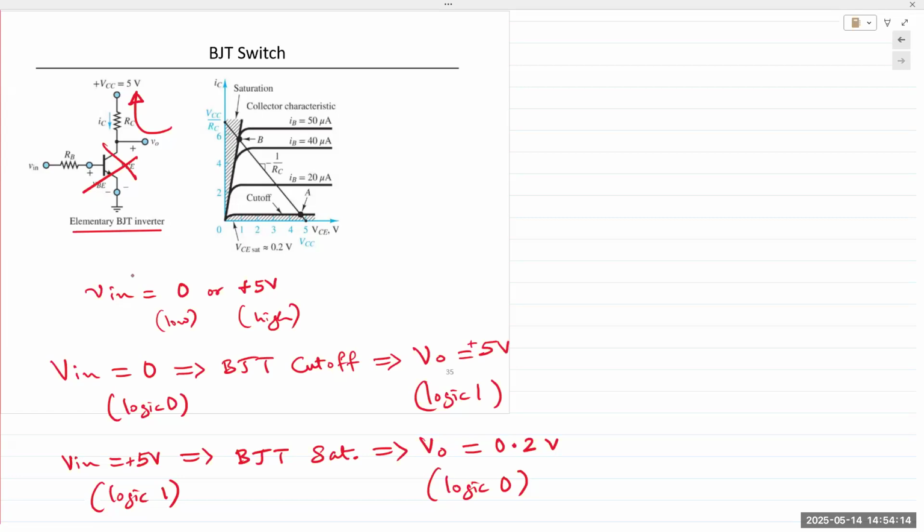So the question being asked is about the example in the reading assignment where the BJT had 2 emitter terminals. And those are used to implement multiple input AND gates, multiple input gates, period. Multiple any kind of gates. So it just depends on how the circuit is configured. So yeah, it is possible that one of them could be forward biased and the other reverse biased. That is absolutely true. It is possible.